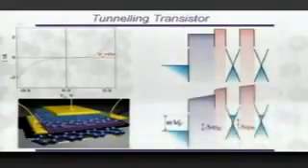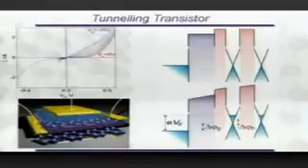We also made a transistor out of it. You put graphene, molybdenum sulfide, boron nitride, molybdenum sulfide, graphene, and then you can gate it, and you can tune the current through this stack, and it acts as a transistor which actually works, and it can be used in integrated circuits. And because it is vertical, we don't have a problem with sizes.